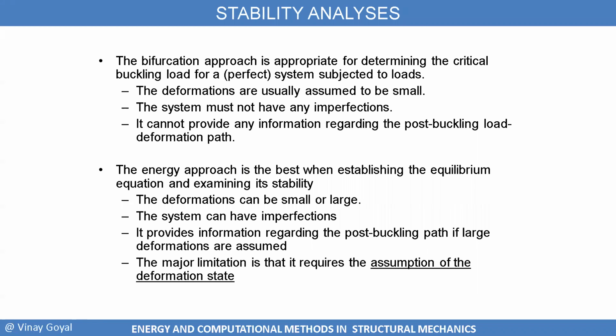The energy approach is best when establishing the equilibrium equation, and we can examine that stability. We want to understand if it's unstable or stable. The deformations can be small or large. The system can have imperfections. It provides information regarding the post-buckling behavior if large deformations are assumed. And the major limitation is that it requires assumption of the deformation state. That is the main thing that needs to be examined.